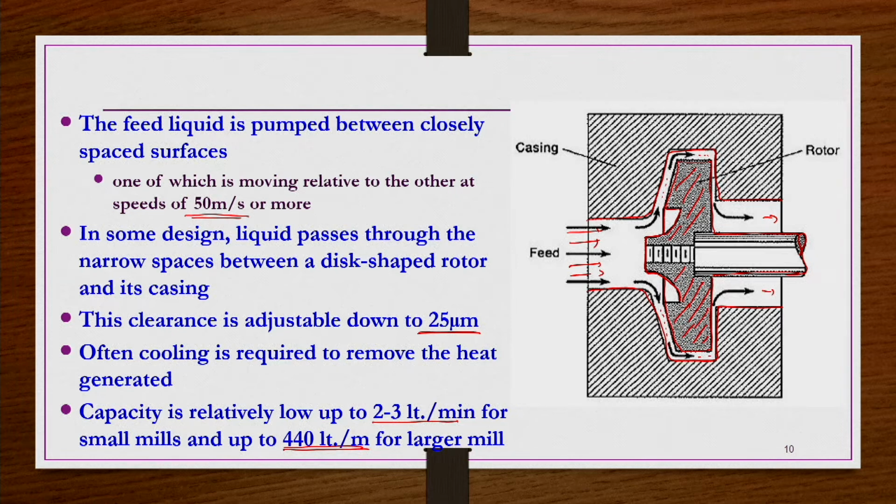So, that is about the ultrafine grinders, for dry and wet products. For dry products, we have to use hammer mills with internal classification or external classification, or the fluid energy mill. For wet grinding under ultrafine grinding conditions, you have to use agitated mills, such as colloidal mills, etc. Now, we see some details about the cutting machines.